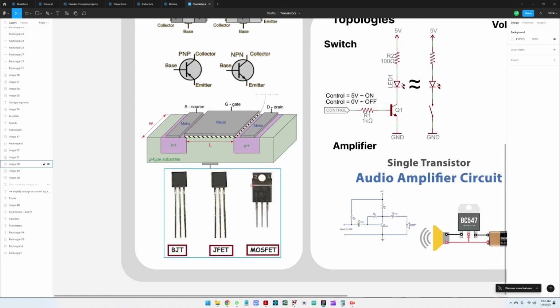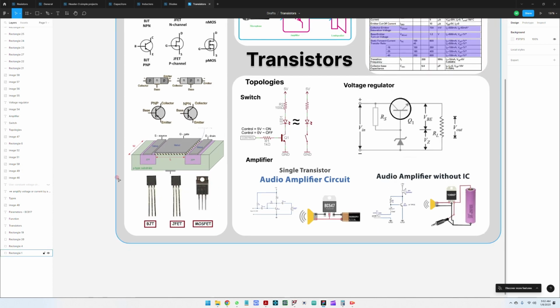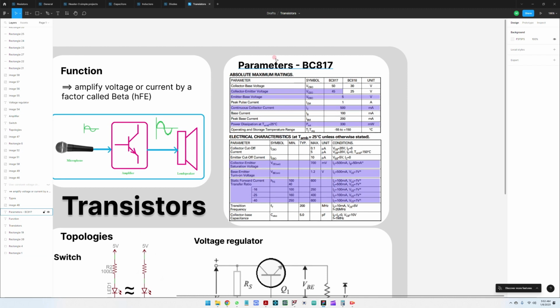So always measure for a MOS transistor, always measure to make sure that you don't accidentally short circuit the cooling pad of the transistor to a voltage level, so that nothing explodes.